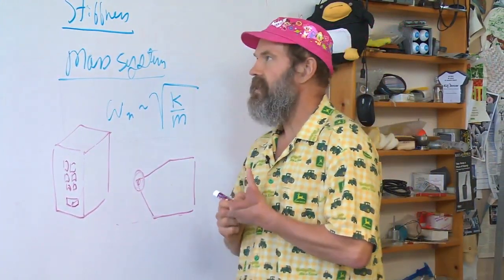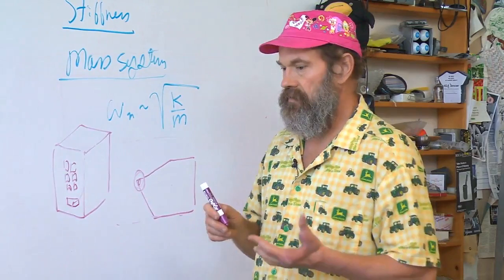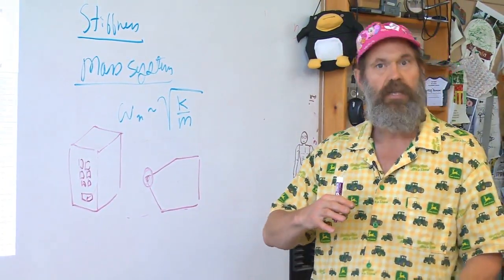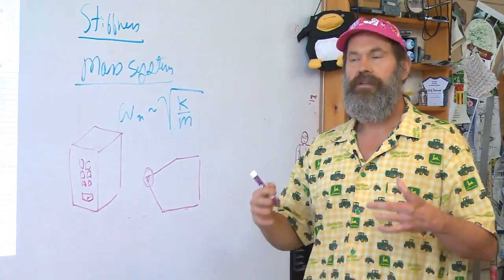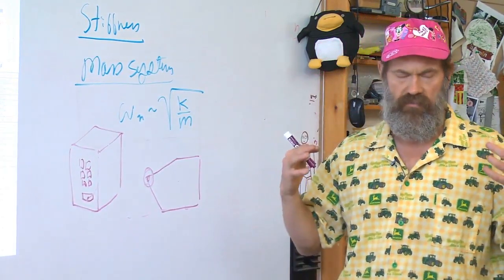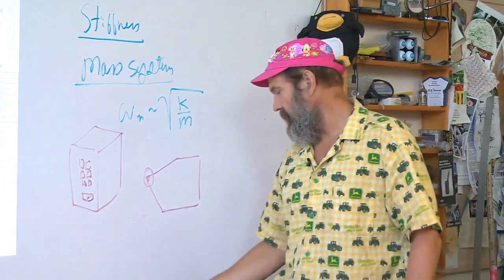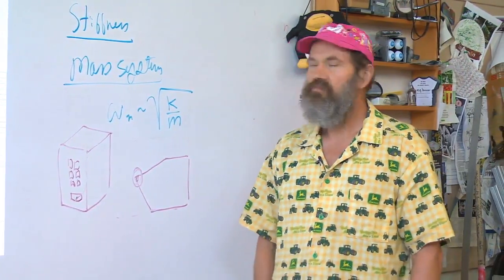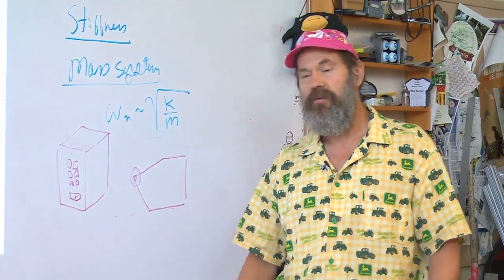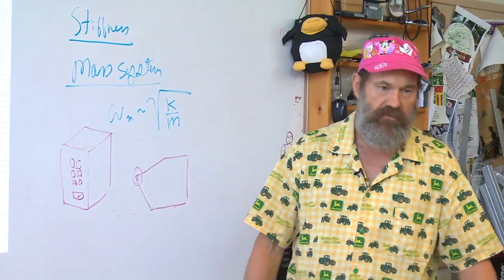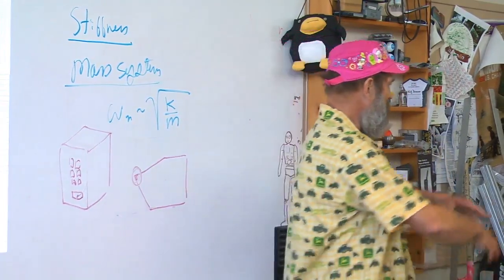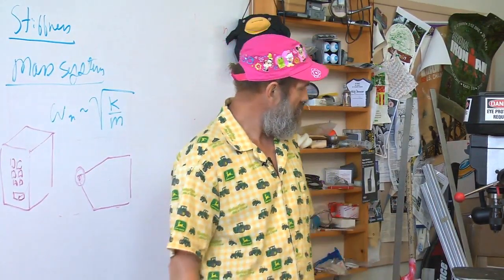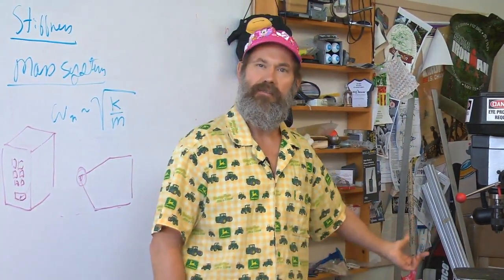So even though you may not intend to have your structure used in a way that could cause an instability issue, you have to assume that it will be misused. How would you attack it? One of the really good ways to do this kind of evaluation on your machine: go find some kids, maybe some teenagers, in the summertime, when they're bored and have nothing else to do. Build a plywood mock-up, something that's safe. Say, okay guys, you're bored, what would you do with this thing? How could you hurt it?